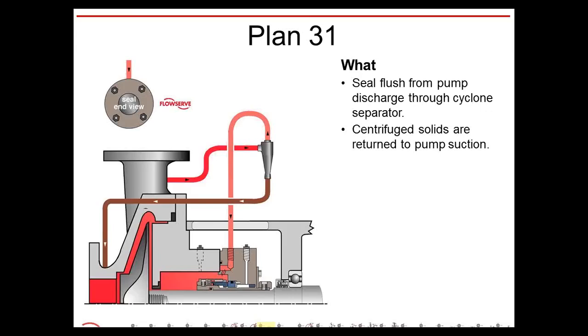There are some factors you have to consider here. Number one, the differential pressures between all of those components all have to fit into a certain design parameter for the cyclone separator size that you're selecting. If you're out of the range, you lose efficiency. You will not get as much solids removal. Second, if you have very viscous fluids or very, very light solids, they will not drop out.